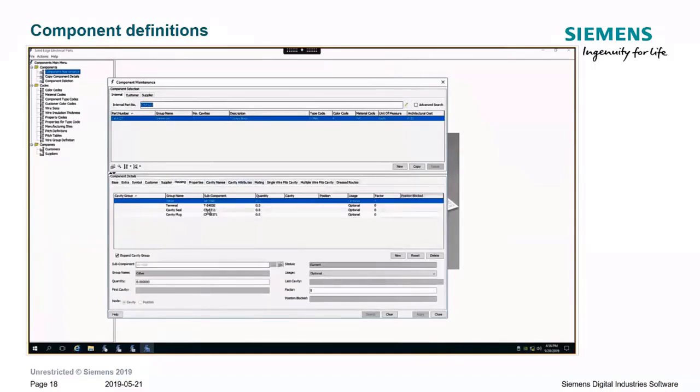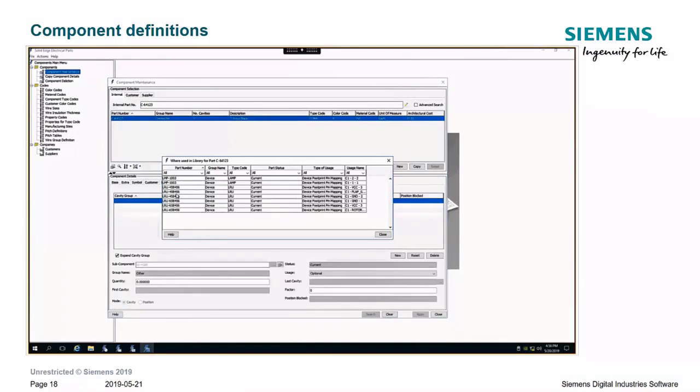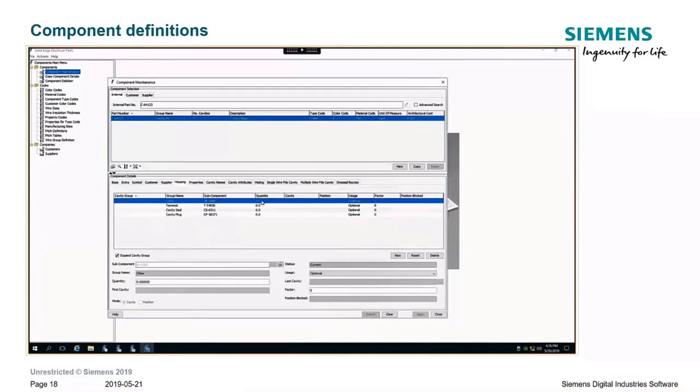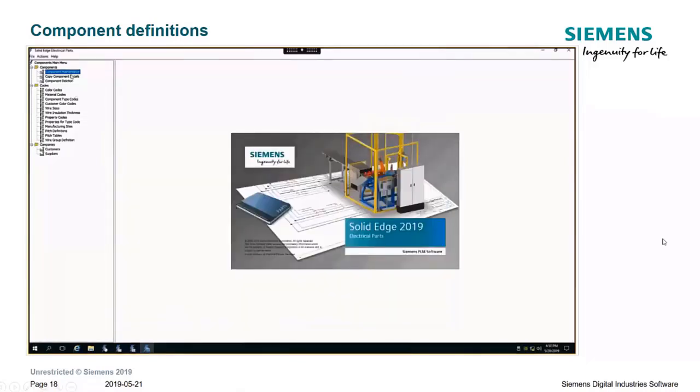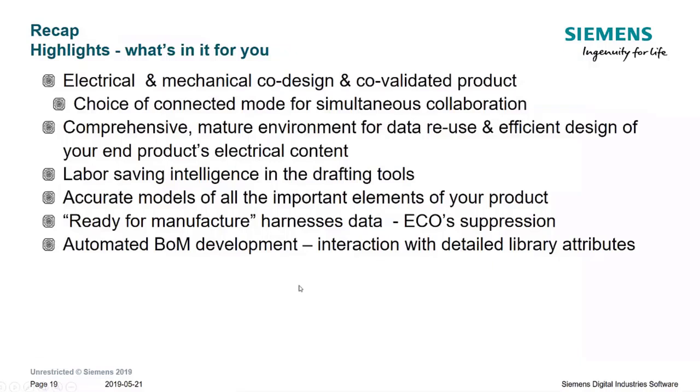Now we saw the subcomponent selection algorithms running. This is kind of simple. It only has one terminal, one cavity plug, one cavity seal, one cable seal, and it has a cover and locking piece as well. The query that was just run was to show where the connector has devices that it mates to the harness side connector, what we call a footprint.